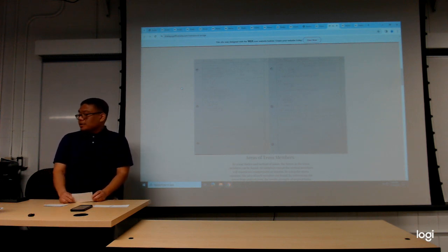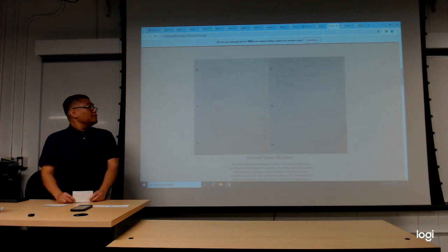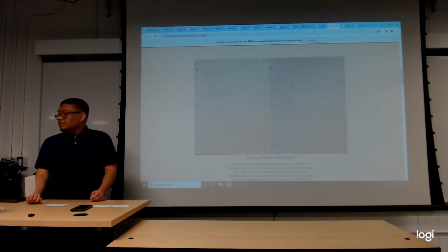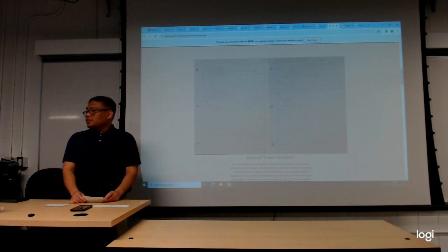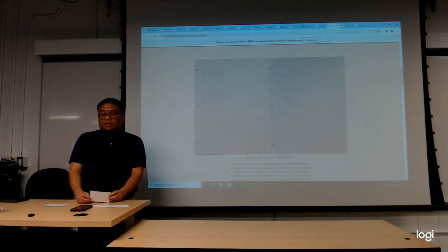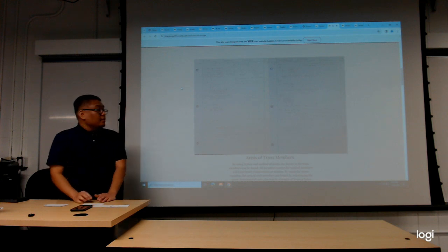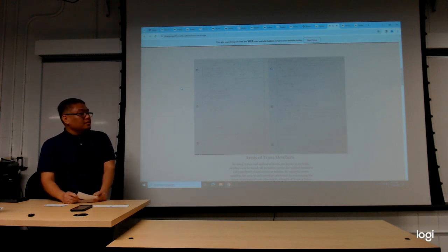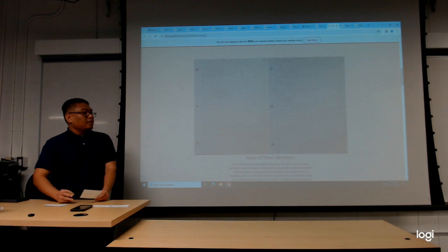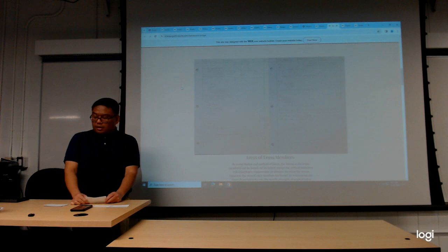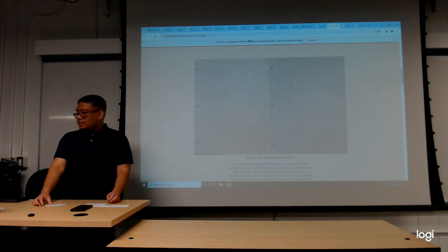So then, by using method of joints, the compression and tension forces are calculated. Then through mechanics of materials, the stress equation can be used in addition to referencing the compressive and tensile strength of balsa wood, and then the minimum cross-sectional area can be found. Then by setting conditions for the size of the balsa wood being square beams and having them be the same cross-sectional area across the whole bridge, the best size for this analysis was 1/2 inch by 1/2 inch.